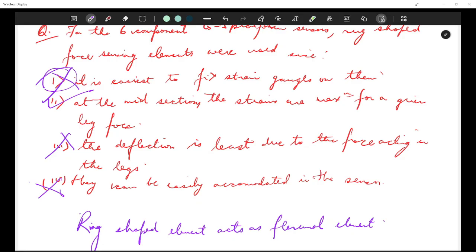The other option is "easier to model and analyze." Flexural joints may even be more complex to model because it is beam theory, it is compliance. Ease of modeling is not the reason. Hence, that option is also incorrect.